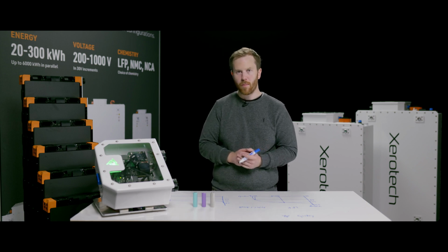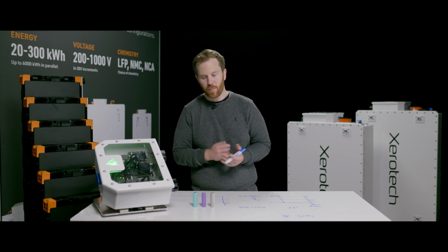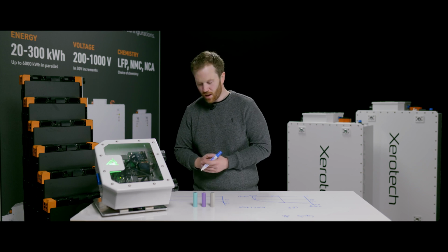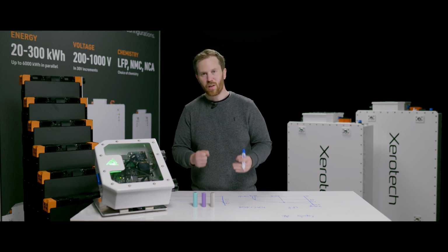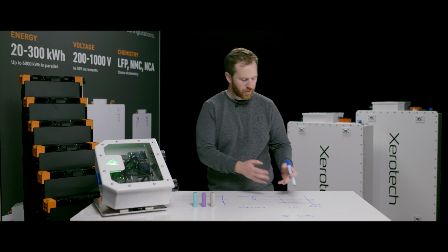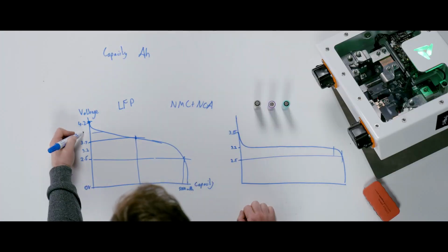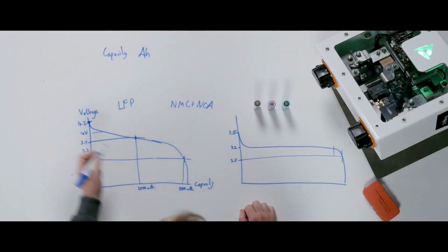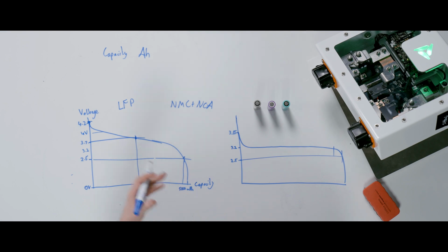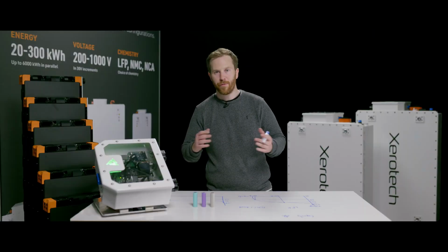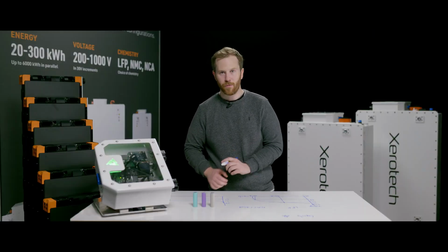It's good from a performance perspective because when the battery is being used, charged, and discharged in normal operation, you don't see a change in performance. In an electric vehicle like a long-range Tesla, you will notice that when the battery is 100% charged, you actually have more power because the voltage is higher. When the battery is nearly full, the voltage is almost 4.2 volts per cell. And if you've got hundreds of cells in series, which we'll come to in a moment, it means the pack voltage might be 400 volts versus 250 volts.